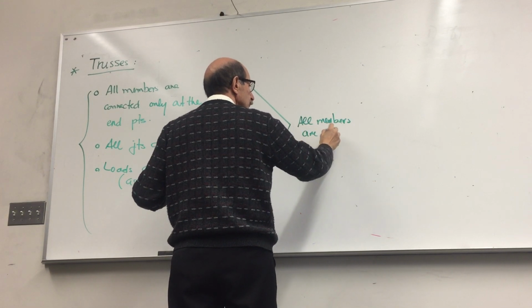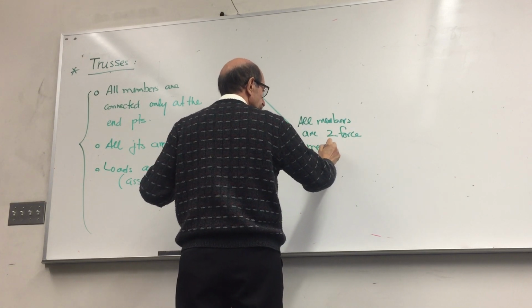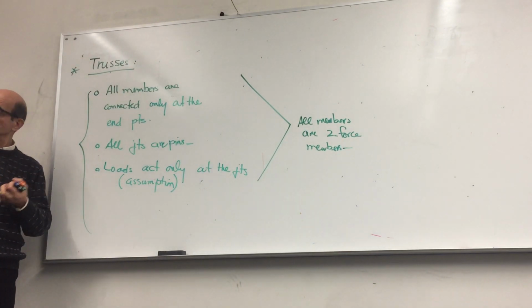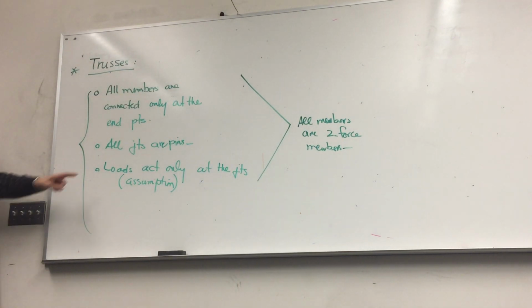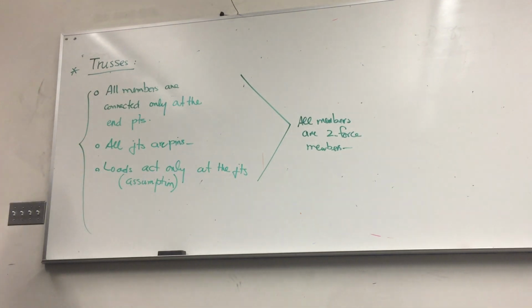are two-force members. But isn't that assuming that there's no force acting somewhere along the bar? That is correct. That's what I said. Loads act only at the joints. Oh, I did see the last bullet point. Yes, sorry. So every single member is a two-force member.